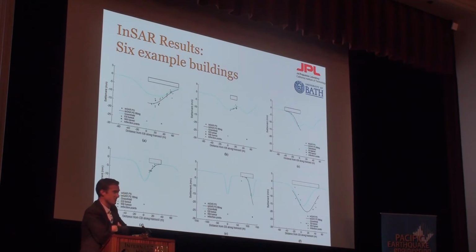So I tried to put some black curves through the black dots, which may or may not convince you in any way at all. But I think it was a kind of groundbreaking study to say, these are only maximum settlements of between 5 and 15 millimeters measured from satellite. So if you're above that level, if you're in the 15 millimeter range, we can do that. We can get building deformation, which we could use to back calculate maybe maximum strains potentially from satellite data.